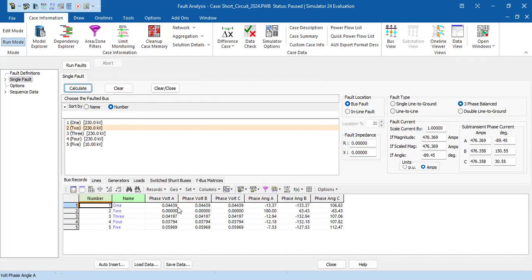So when you do something in one bus, it affects, or it should affect, all the buses. So if a fault happens on one bus, meaning that one of the phases at that bus goes to ground, it will affect the current and the voltages seen at the other buses. Alright? Every action has an equal and opposite reaction.